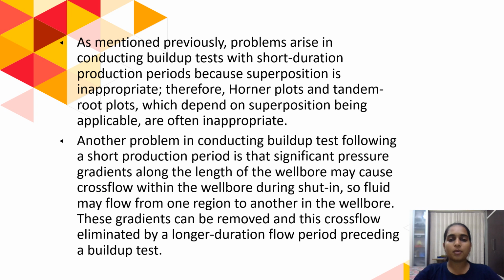As mentioned previously, problems arise in conducting build-up tests with short duration production periods because superposition is inappropriate. Therefore, Horner plots and tandem root plots, which depend on superposition being applicable, are often inappropriate. Another problem in conducting build-up tests following a short production period is that significant pressure gradients along the length of the wellbore may cause cross-flow within the wellbore during shut-in. So, fluid may flow from one region to another in the wellbore. These gradients can be removed and this cross flow eliminated by a longer duration flow period preceding a build-up test.